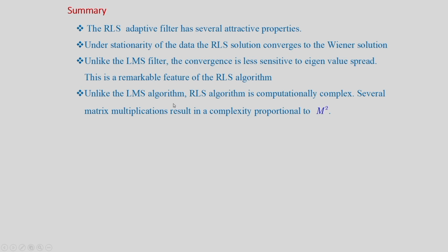Unlike the LMS algorithm, the RLS algorithm is computationally complex. This is the disadvantage of RLS filters. Several matrix multiplications result in a complexity proportional to M squared.